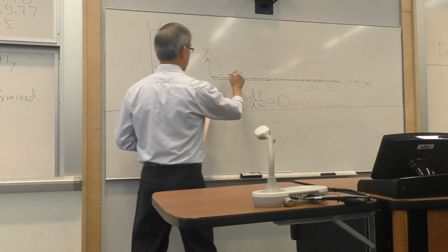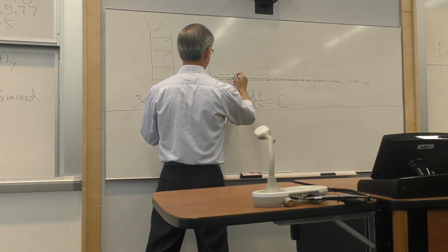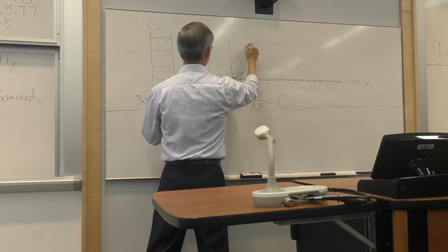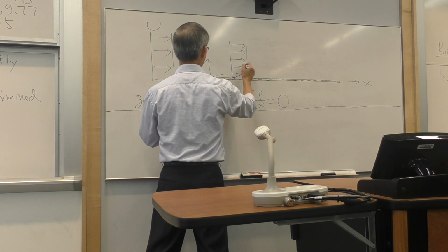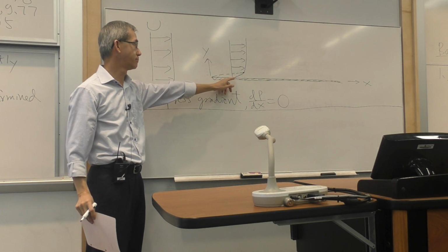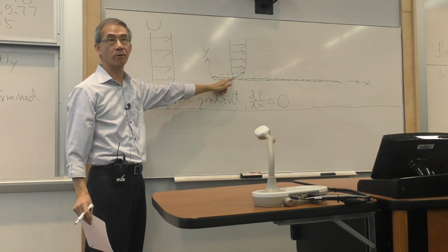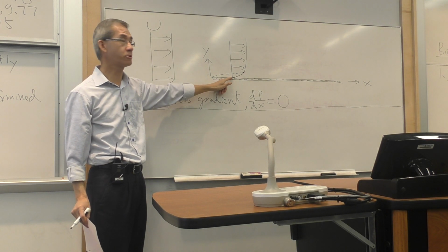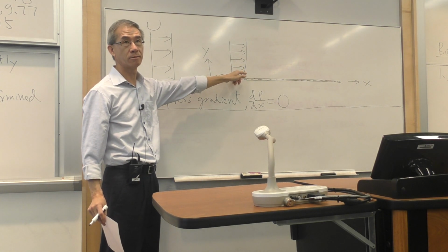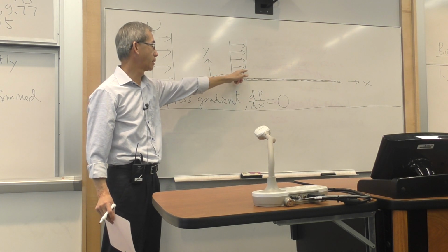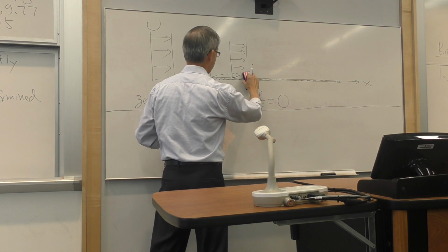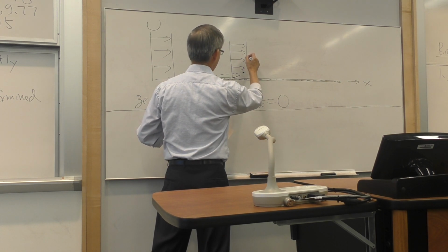So close to the leading edge, I will have a velocity distribution that, very near the plate, has zero velocity at the wall, the so-called no-slip condition. And then at a finite distance delta away from the plate, I have a uniform flow. I didn't draw the diagram very well, so let me make some detailed corrections.